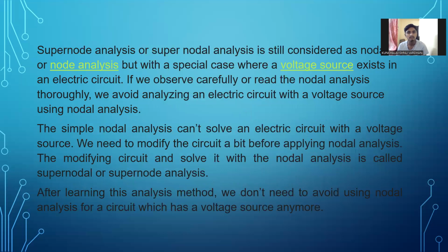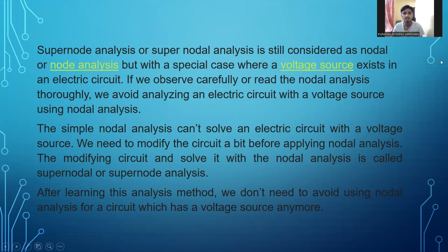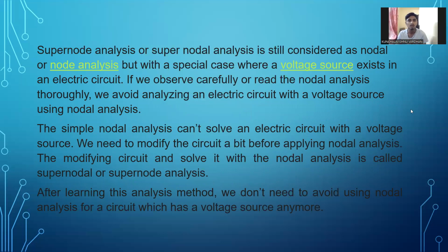Supernode analysis, or supernodal analysis, is still considered nodal analysis, but with a special case where a voltage source exists in an electric circuit. If we read the nodal analysis thoroughly, we avoid analyzing an electric circuit with a voltage source using nodal analysis. The simple nodal analysis can't solve an electric circuit with a voltage source.